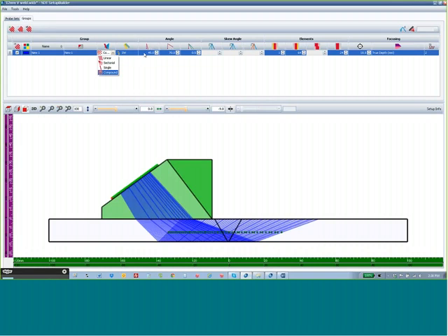Again, the scan plan is dependent on the user not programming angles outside the steering range of the probe, and almost all shear wave probes from Olympus or other manufacturers are designed for a 40 or 45 to about a 70 or 75 degree S-scan. Once this is configured, file, export, law file.